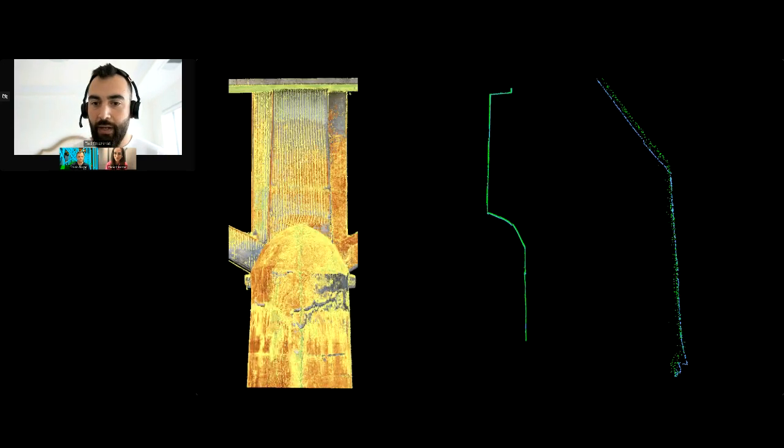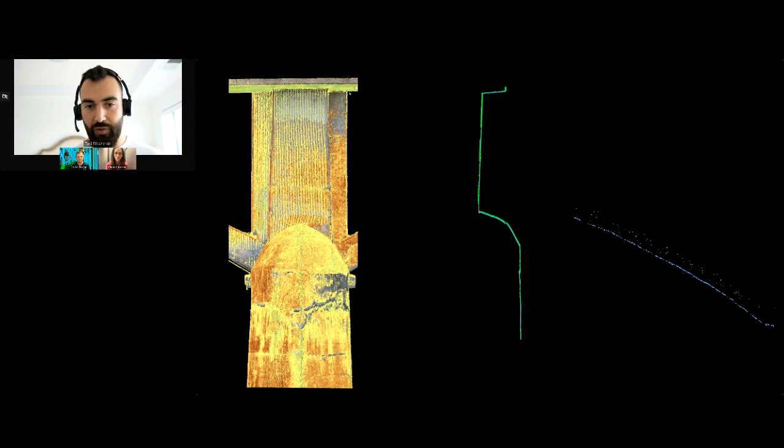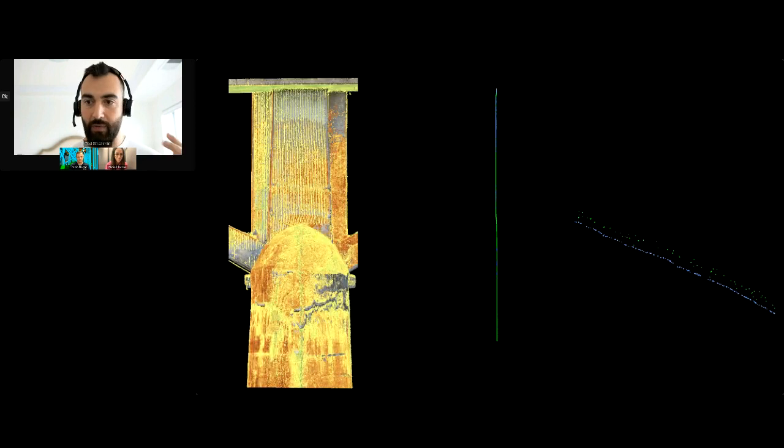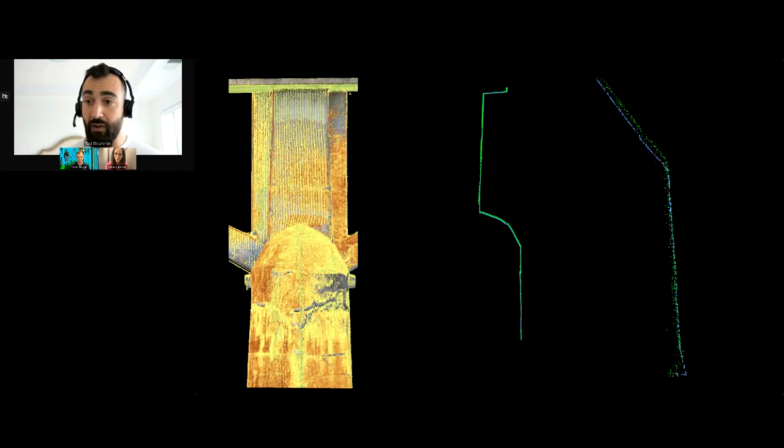Again, let's look at some sections. I picked this pier here. You can see certain areas, it's right on the money. Other areas, there's a little bit of deviation. There's some registration error here to account for too, so not all of the points are valid, but it shows you that the overall shape and relative accuracy of the scan is pretty close for photogrammetry. It gets it to what you would be very, very comfortable with to use in inspections or many use cases or visualizations.